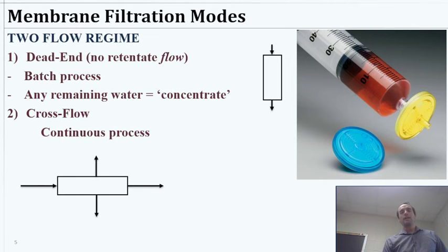So you'll recognize pretty quickly that there's an issue with clogging filters. Fouling is the technical term, that we might need to deal with. There's a limit to how much filtration you can do with a given filter if you've got fouling going on, right? And there's a pressure increase, and at some point, something in your system will probably fail.